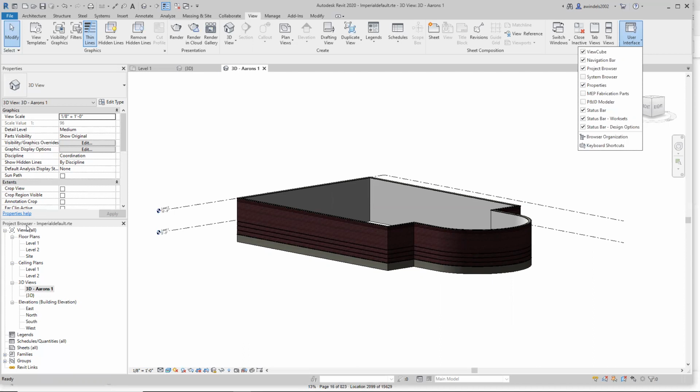A lot of traditional CAD, the workflow is a lot different than that. You have a lot of drawings that make up a large drawing that are referenced into it. And most Revit models, they're all contained in one drawing as much as possible, if not most times. And your project browser helps you do that, to bounce around different views of the same model. So everything is mostly self-contained in one model.